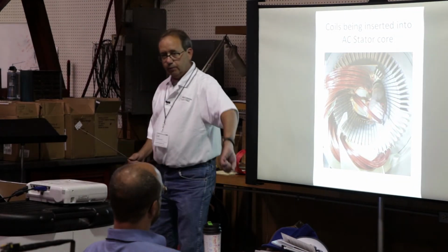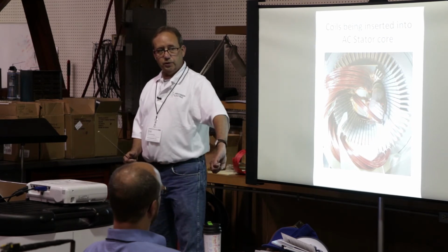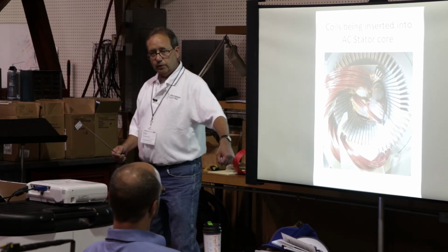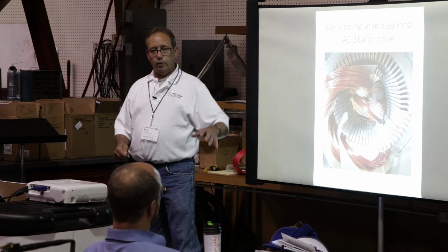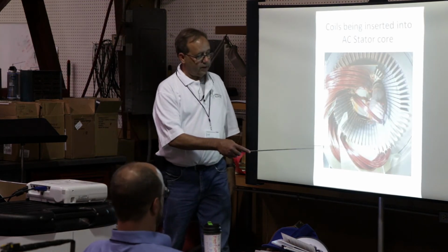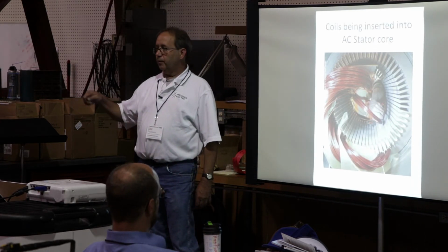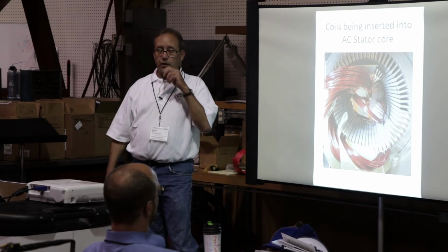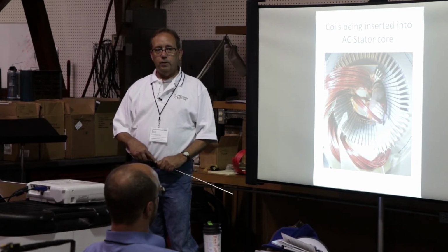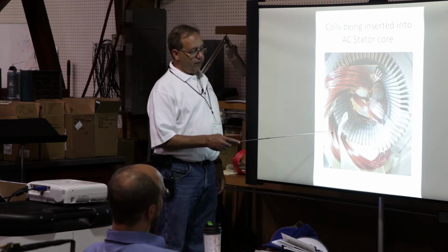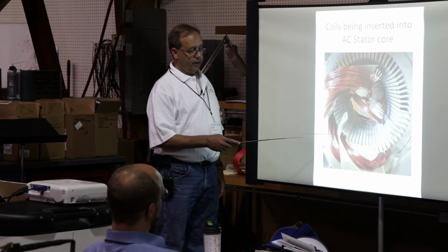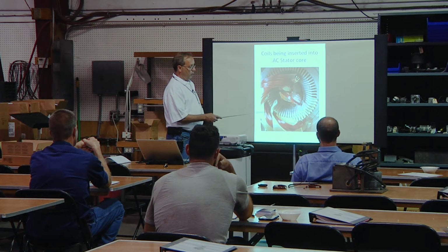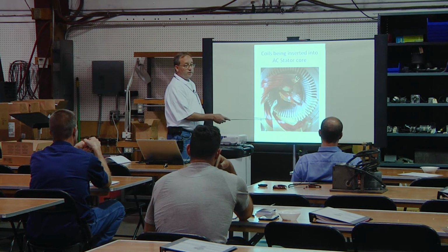Physically rotate it, put it on, put the next one on straight, turn this one, so that essentially what we're doing is, by doing that in A phase, we're changing the polarity of each pole, because it changes the direction of current flow within the coil. So if this is A phase, then it's going to be, say, at any half cycle, a north pole. At the same time, this is going to be B phase, and it's going to be a south pole.